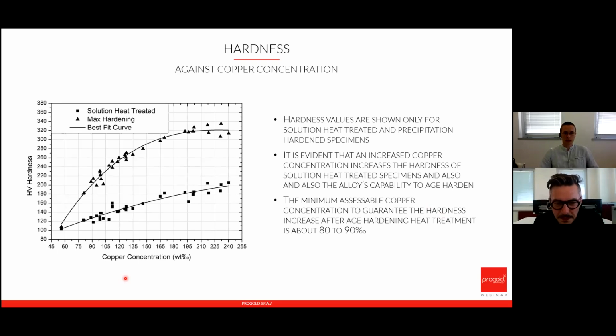Yes, exactly. As we say, 2N color is the lower limit of the hardenable alloy. If you use a color brighter, so yellow brighter or whiter than the 2N standard color, it's very difficult to get a hardenable alloy in 18 karat.